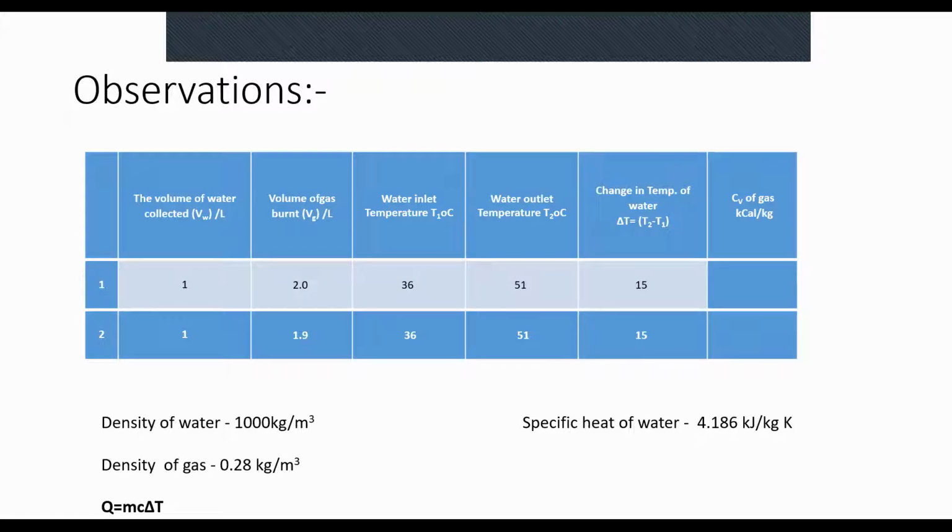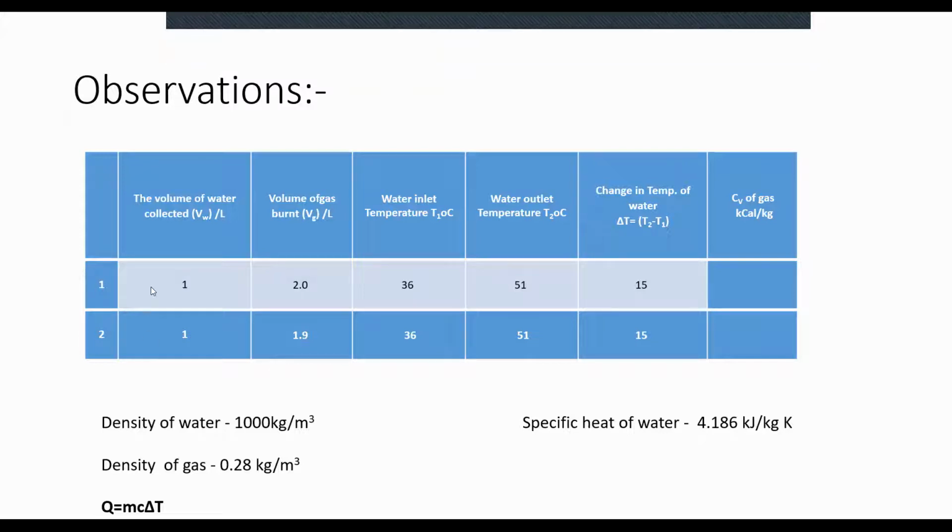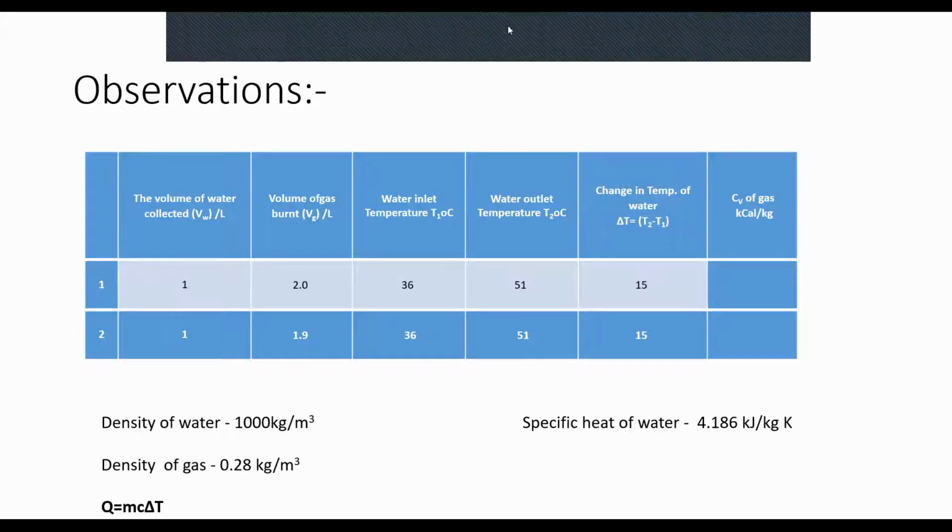You can see that the second time when we collected the 1 liter, the burned volume of LPG gas is 1.9, right? So there will be different values for that, while the other things are the same, so different values for the two sets of data. You have to take the average as the calorific value of the LPG gas. So we will watch the video.